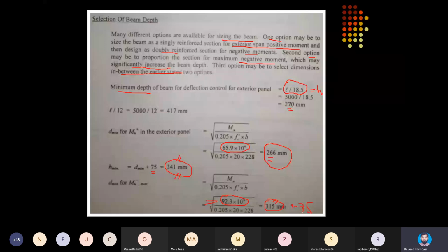So if neutral axis at section 4 and 5 will be within the flange, then section 4 and 5 will also be designed as wide rectangular sections, because the T-beam effect will not be coming because section in compression is still rectangular.